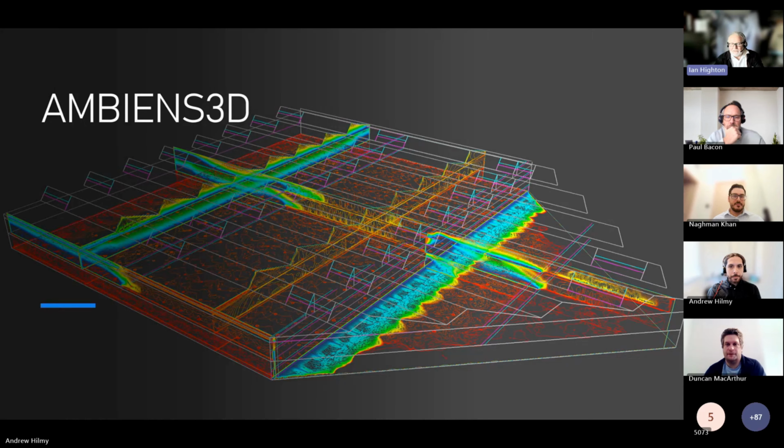I spent a long time bashing my head against this because it's not a great process. It was absolutely innovative in the 1970s when it came out of Imperial College, but you're basically using an omnidirectional variable pressure to try and alter what is often a mass imbalance in one direction, X, Y, or Z. I haven't proven it, but I would possibly guess that pressure correction is unconditionally unstable. So this was the big impetus to try and come up with a much more robust and hopefully better placed tool for people to use within the built environment.